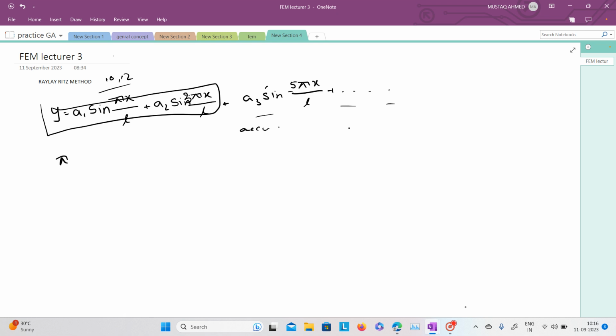Now, pi equals U minus H. Here pi is called the total energy, U is the strain energy, and H is the potential energy. This is classified from physics: total energy equals kinetic energy plus potential energy, but due to gravitational force or some forces, the minus came here. Leave that, this is okay.